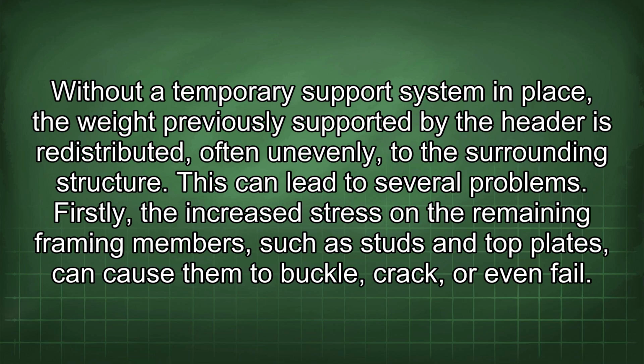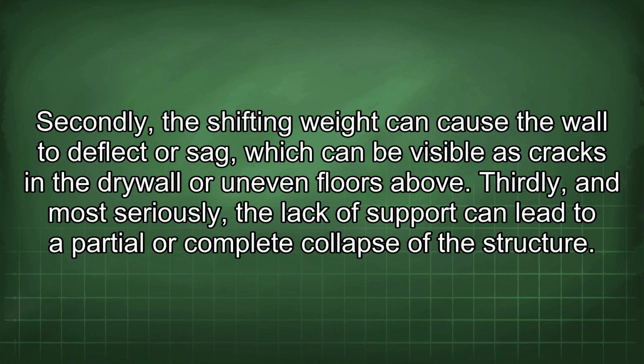Firstly, the increased stress on the remaining framing members, such as studs and top plates, can cause them to buckle, crack, or even fail. Secondly, the shifting weight can cause the wall to deflect or sag, which can be visible as cracks in the drywall or uneven floors above. Thirdly, and most seriously, the lack of support can lead to a partial or complete collapse of the structure.